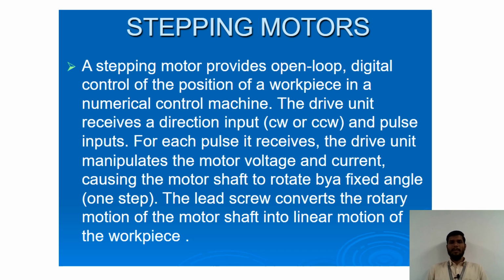Stepping motors. Stepping motors are important element of drive system. A stepping motor provides open loop digital control of the position of a workpiece in a numerical control machine. The drive unit receives a direction input clockwise or counterclockwise and pulse inputs. For each pulse it receives, the drive unit manipulates the motor voltage and current, causing the motor shaft to rotate by fixed angle, one step. The lead screw converts the rotary motion of motor shaft into linear motion of the workpiece.